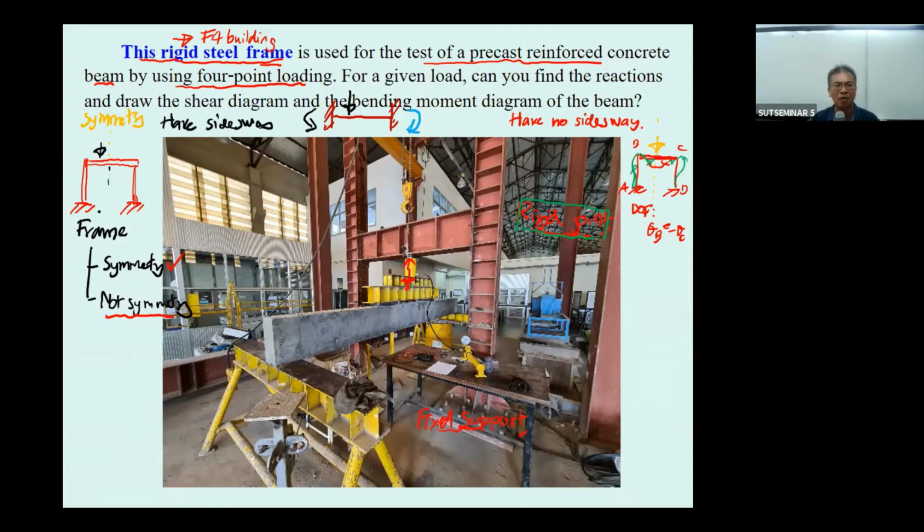The fixed end moment at point B is larger than the fixed end moment at point C. So the distribution of the force may cause the deformation to be something like this, with some sidesway. Due to this, the elastic curve will be something very similar to this, in which we still have the normal angle at joint B and joint C.